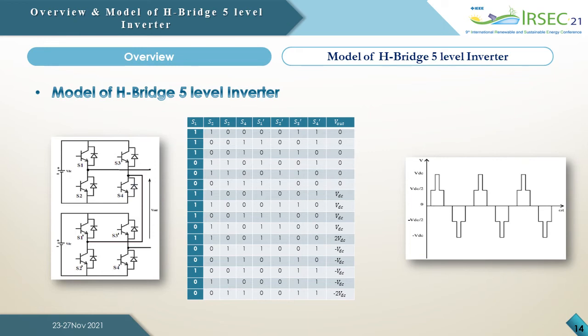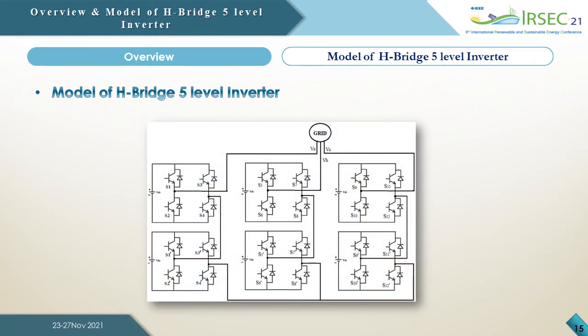For this work, we are using an H-Bridge 5-level inverter for the many advantages they have in terms of THD factor reduction. We start our modeling using the electrical model of an H-Bridge 5-level inverter single phase as shown. So the 5-level output waveform is obtained by respecting the following switching state of the used semiconductor. And by using 3 of the previous model, we obtained the model of the H-Bridge 5-level inverter.